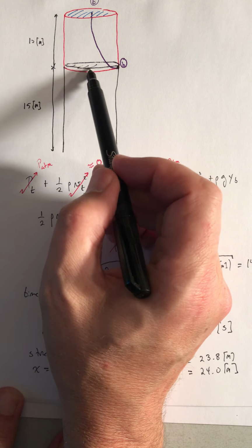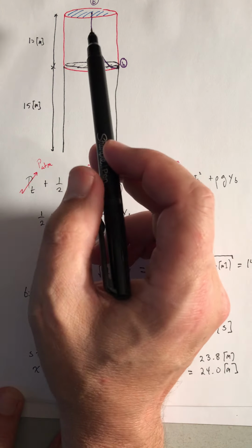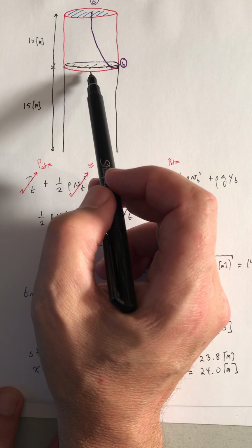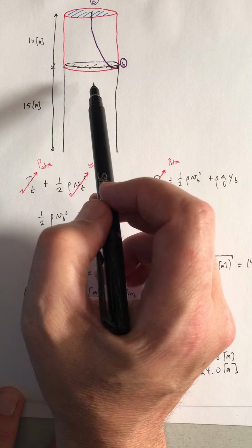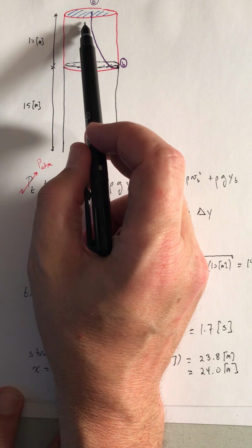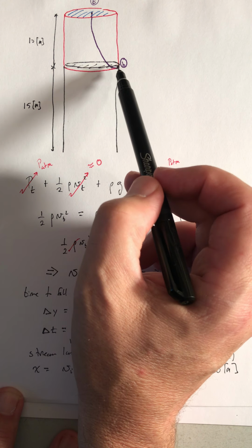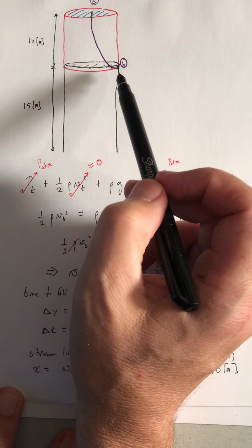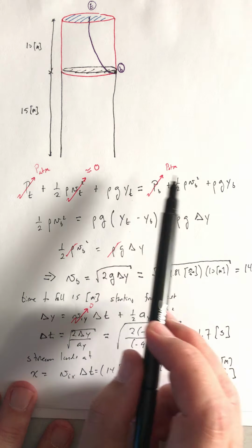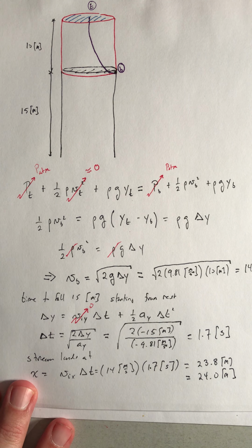That layer of fluid is having to support the weight of all of the fluid above it, and therefore the pressure is higher at the bottom to let the fluid be in approximately hydrostatic equilibrium. As the fluid level drops, the pressure at the bottom is going to decrease, and so the fluid is going to come out at a slower speed. So everything with how pressure changes with depth within the fluid is also there in Bernoulli's equation.